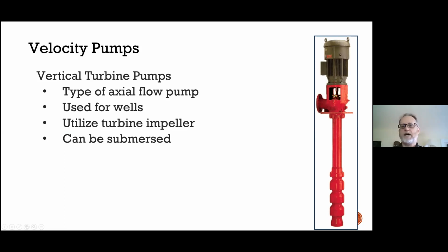It then enters the eye of the next impeller, turns, and that speed converts what is already an increased pressure head into a higher pressure head, and so on and so on. So we have what we call a multi-stage centrifugal pump. A very typical application would be suspended into a reservoir, a concrete or steel tank that is full, pumping further up to a higher elevation somewhere else in the system.